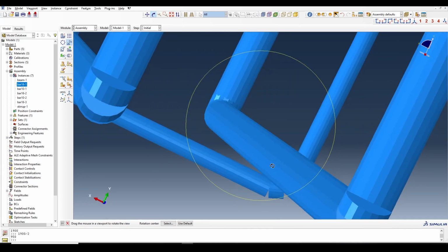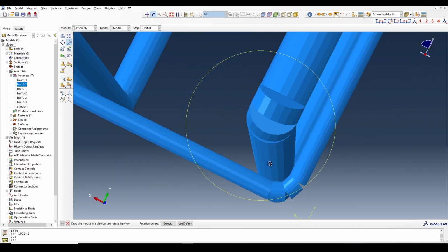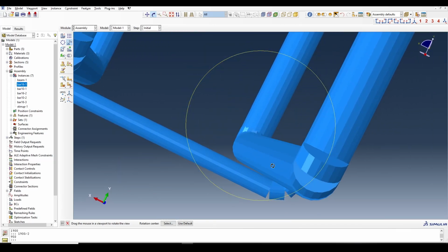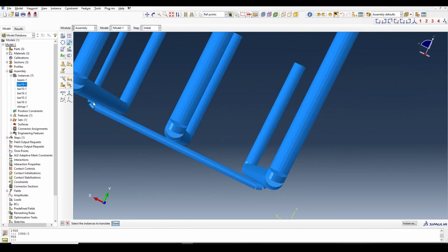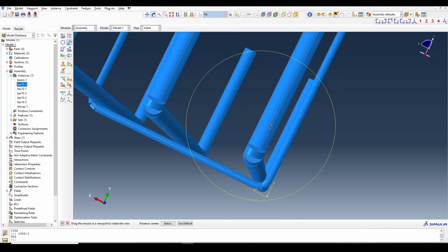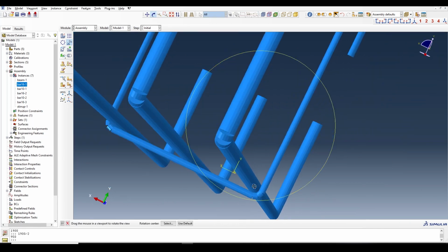This bar should touch the stirrup at least. Okay, here is little gap. Again click on done, press enter. Now 0 comma in y direction 0.5, I think. 0.5 comma 0, that will be fine.